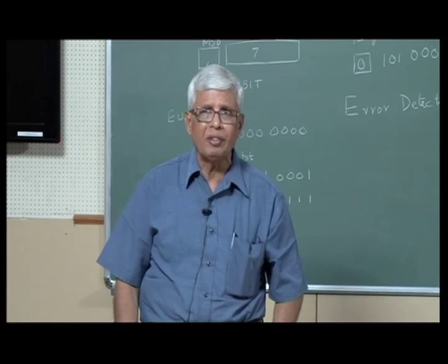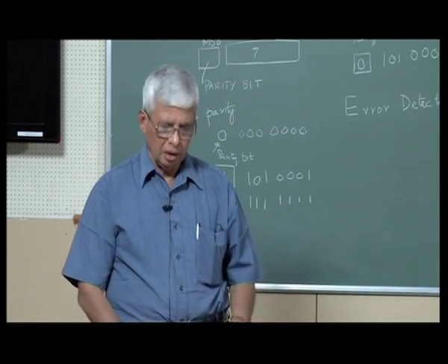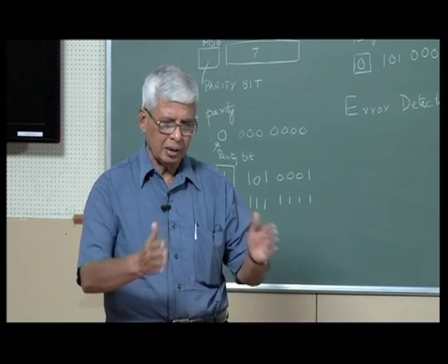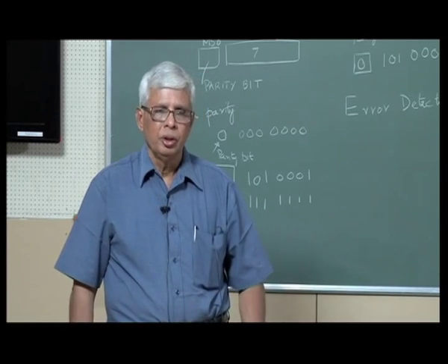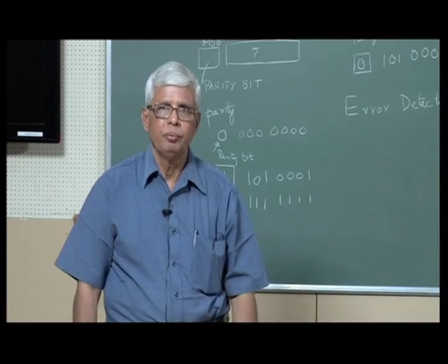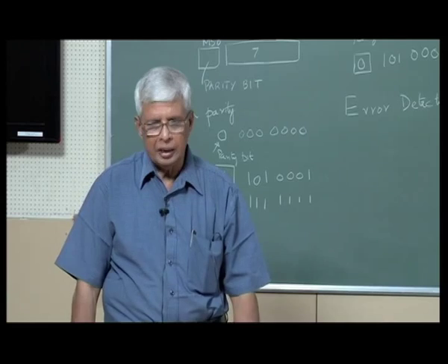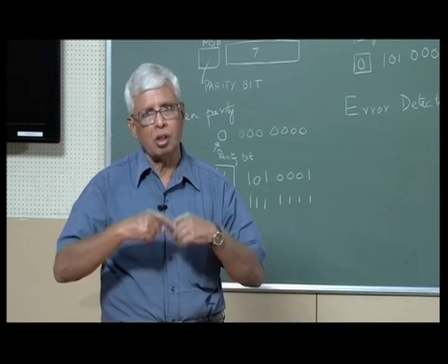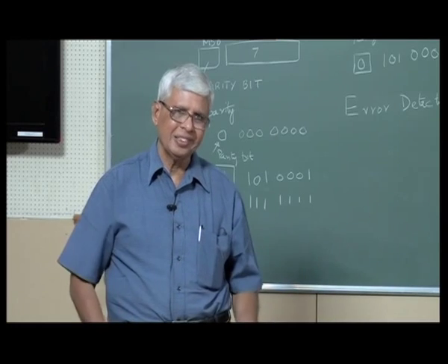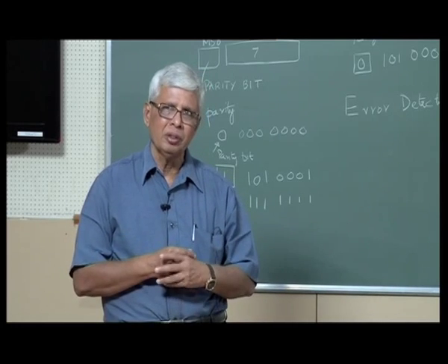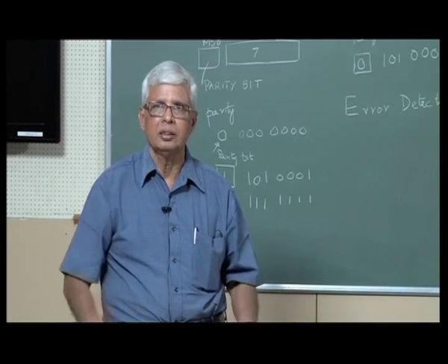Usually they don't do it for every bit or every data word. The messages are packed as data strings, let us say 16 words. At the end of 16 words, even if one of these words is wrong, you will ask them to repeat all the 16, because it is not possible to say every time that 1 bit is missing, and your total communication is delayed.